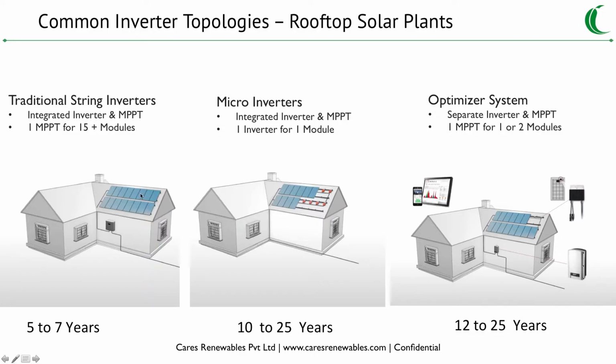The solar panels are connected in series, so there is a high voltage DC present. Each module typically has a VOC around 48 volt. Let's assume it's 50, so if there are 10 panels, it's 500. If it's 20, it's around 1000. And if you have multiple strings, typically the systems which we have in rooftop are all 1000 volt DC systems and never exceed 1000.